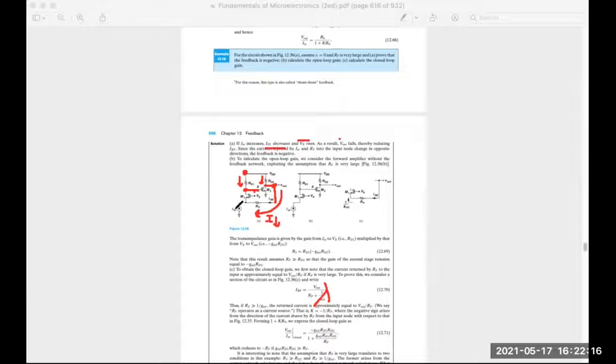So as you can see, when we have an input increasing, this input current would want to increase, but you are getting a negative correspondence. It's in correspondence to that action. This feedback structure is taking a reaction and it's decreasing this current. So this current is not really increasing much because your feedback structure decreased this current. Okay? That's why it's called negative feedback.